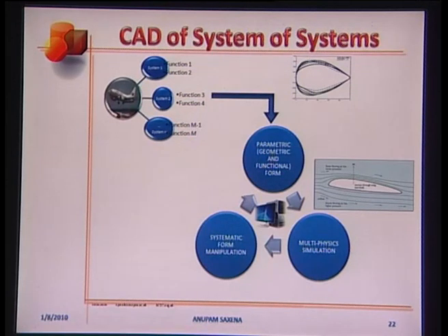Computational fluid dynamics, or CFD, is performed to analyze the flow pattern around it. The data is used to estimate the lift, say. The positions of the control points are appropriately updated to improve the lift. As a result, better airfoil shapes can be obtained. This illustration shows the airfoil contours at different cross sections of the wing of Boeing 737.